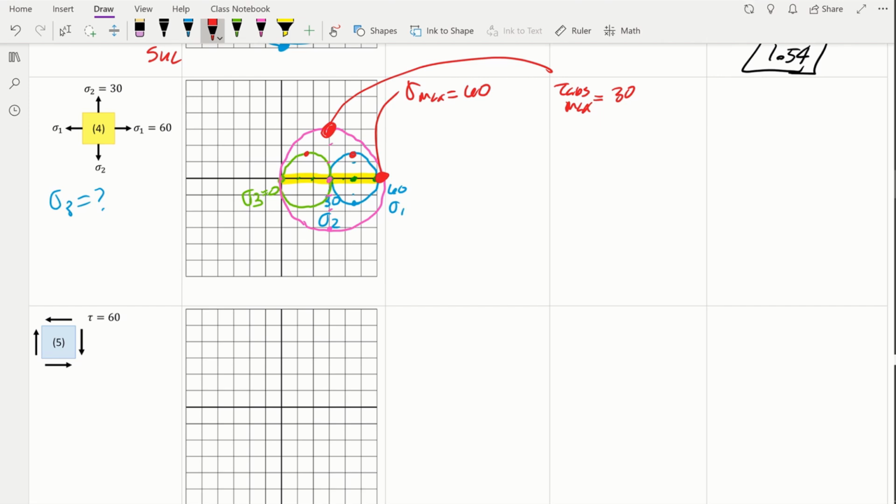Okie dokie, let's calculate some safety factors. Maximum normal says that the maximum stress expected, which is 60, cannot exceed the ultimate tensile, or in this case the yield strength. So we got 160 divided by 60. This is going to give a safety factor of 2.67.